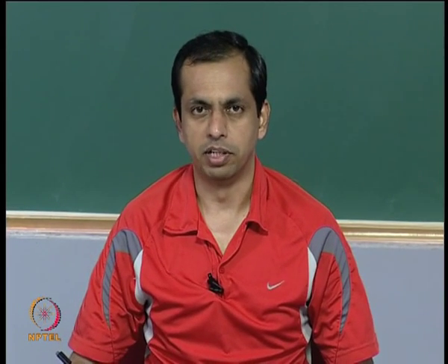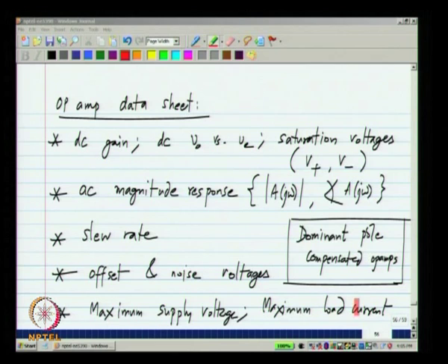And welcome to lecture 19 of analog integrated circuit design. In the previous lecture, we were looking at a typical op amp data sheet, what specifications are listed, and this we did based on our knowledge of op amps so far, as a macro model using transconductors or voltage controlled current sources. What we listed as typical specifications of a standard op amp are given here.